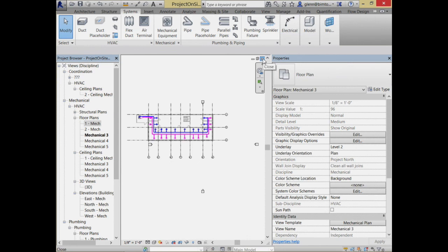You certainly can. With this system, you just had one air handler on one floor, and then the ducts going up. Does it make sense to have an air handler on each floor, or should we just have one per building? It really gets to your overall strategy. Very often it will be a single air handler in one location, down at the bottom or up on the roof. Then there will be a series of valves that control the amount of volume flowing through each of the different floors based on their needs. So it's quite common to have one big air handler, depending on the size of your building, pushing all the air, and then valves controlling the amount of flow to each of the different branches on the different floors.